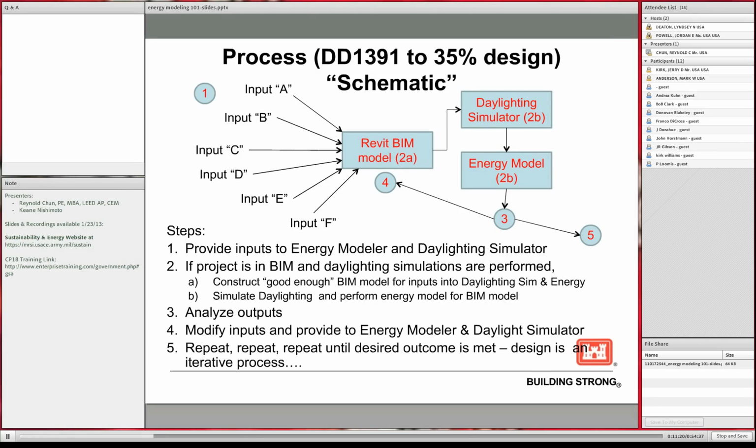If a BIM model is available, there is technology that can quickly transfer data from the BIM model or Revit model over to the energy modeling software. There are also some Revit or BIM tools that can do energy modeling. It's just that at this time, I'm not too sure that it is quite proven yet. So I would really rely on using eQUEST or Carrier HAP.